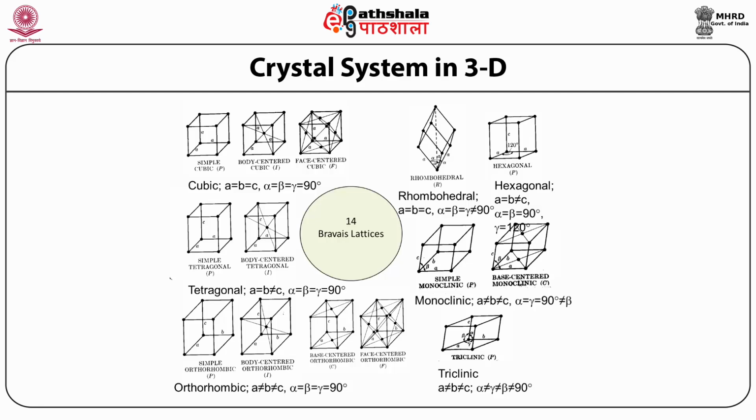Accordingly, 14 space lattices are divided into 7 crystal systems. They are triclinic, monoclinic, orthorhombic, tetragonal, trigonal, hexagonal and cubic. All these structures are shown in this slide. If a crystal has no symmetry, then the point group is 1, or the center of symmetry is 1 only. Then there is no restriction on the shape of the unit cell. All 3 angles alpha, beta and gamma have to be specified, and hence the system is called triclinic, or occasionally an orthic system. A monoclinic crystal has two-fold symmetry in one direction only.